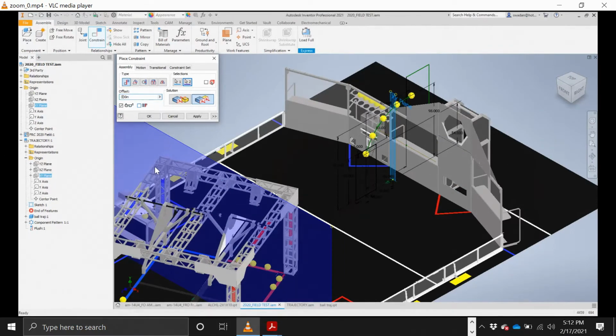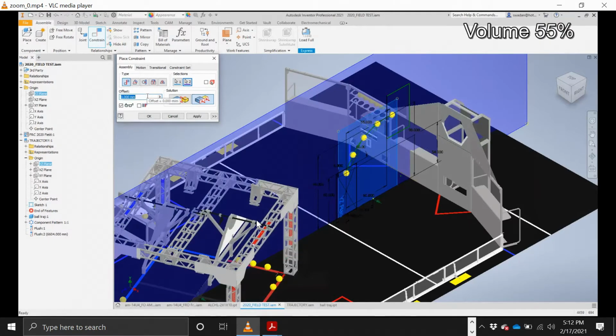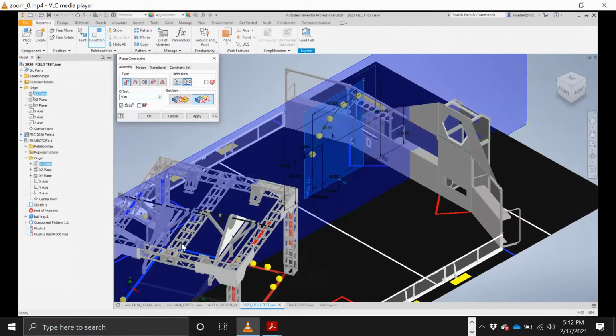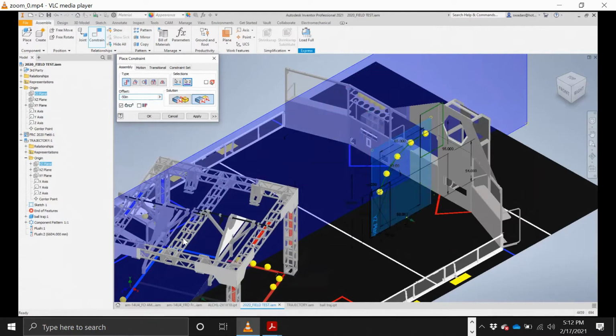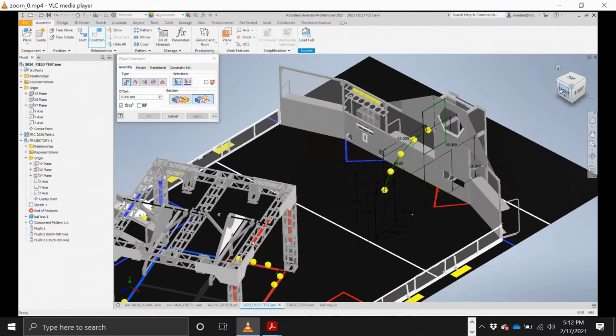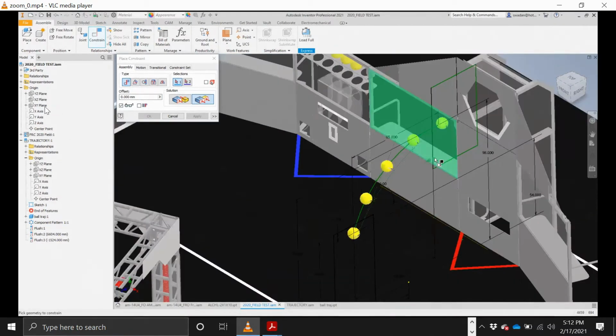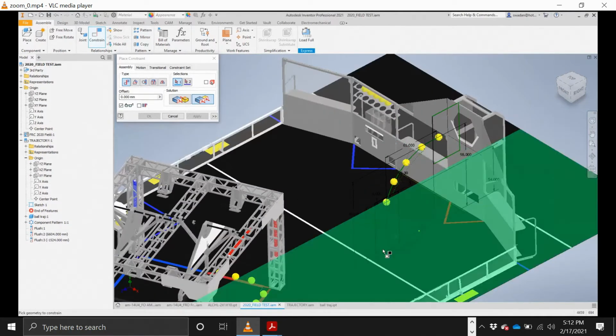I'm going to say that it's probably going to be about 260 inches away from the center of the field, and I want to mate everything to the origin planes that we mentioned before, because what happens is if you mate it to the field itself and then the field goes away, it's going to give you a bunch of errors. So we don't want that. So we're going to mate it to the origin as much as possible.